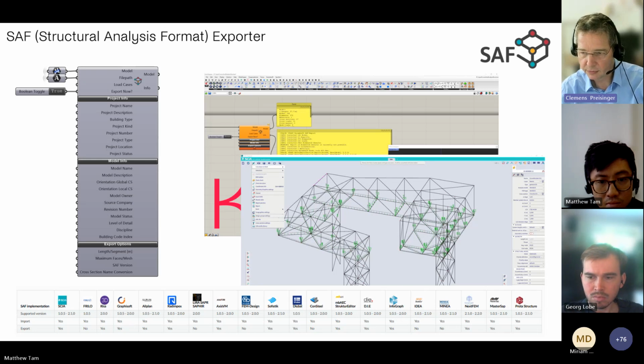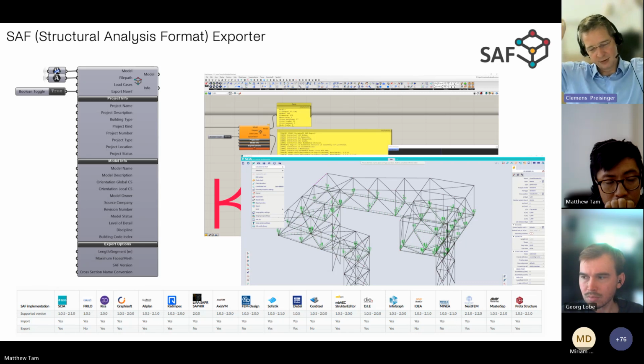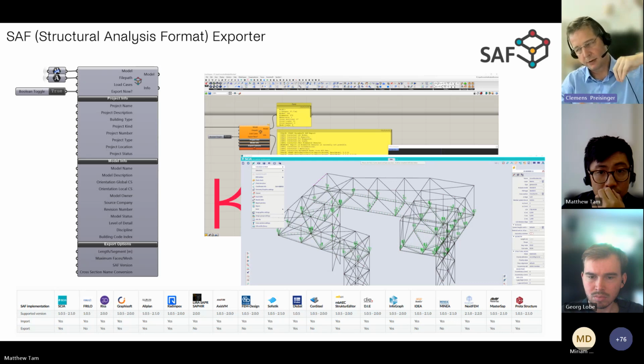Mesh load creates one-way loads. Can we expect a feature that does something similar for two-way load distribution as well? In fact, the mesh load component is not aware of directionality. It simply takes the loads which have been generated for the mesh vertices and places them on the nearest support or nearest structure point in Karamba. And in case of nodes, you get a nodal load, or in case of beams, a uniform distributed load is currently created.